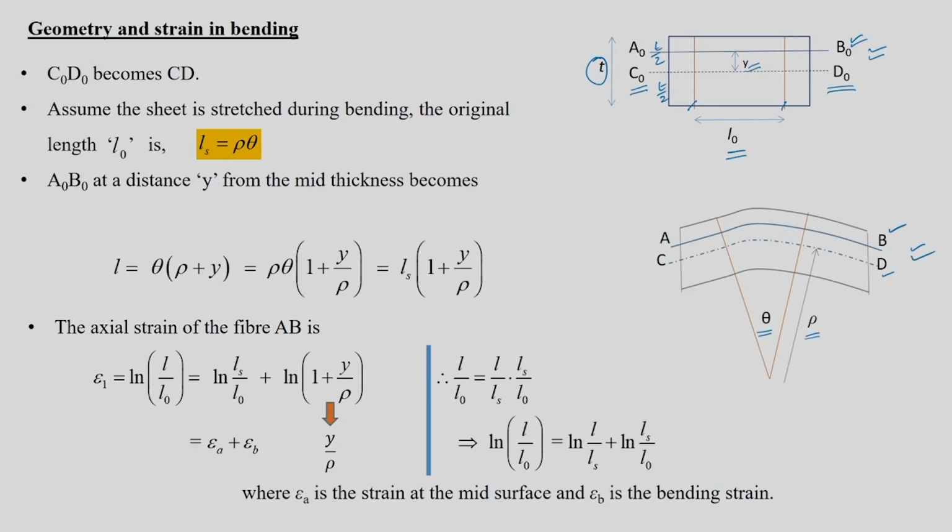Of course, here we cannot put circle grids and evaluate strain, unlike in other deformation processes where we put circle grids on the surface. Here we are discussing sheet bending, and we are looking at a section. That is why thickness is given here. Why are we showing a section when we have a bend? The bending is done with respect to this axis, isn't it? So why are we showing a section? We will see in the next slide. But before that, we cannot put circle grids and evaluate because the sheet thickness would be maybe 1.5 to 2 mm. So naturally we have to get it in a different way.